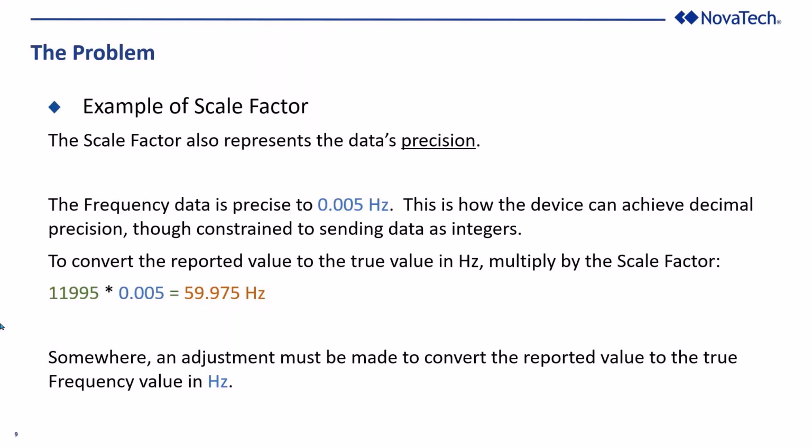The substation RTU would be a fairly common place to do that, but in a lot of cases, the SCADA master might bring in the data and make the adjustments itself before that data gets archived. We're probably going to go through the rest of this presentation under the assumption that here's how you make this scaling adjustment in the RTU. Though keep in mind, especially for our Orion SCADA users, you can make these adjustments by doing the same thing I'm showing you on the Orion SCADA master too.